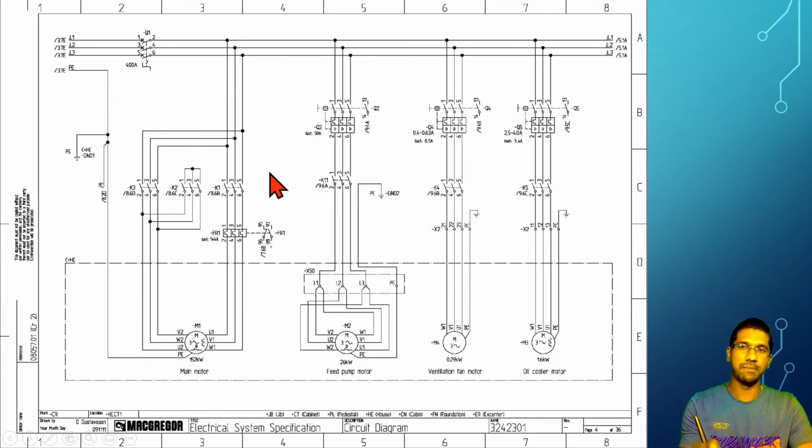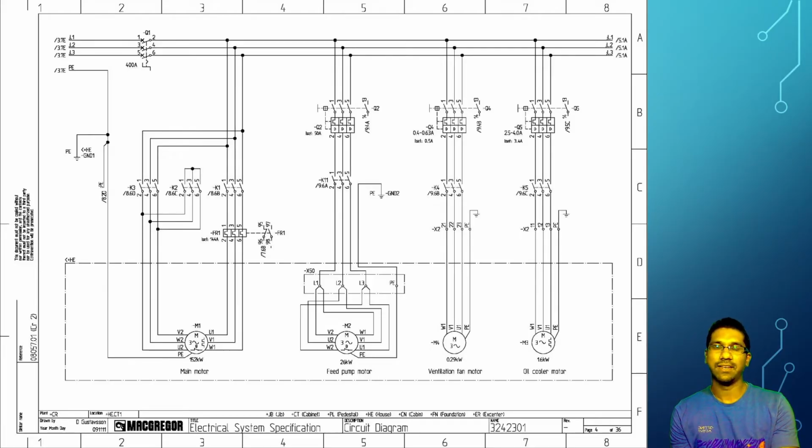If you want to find a component, there are many components in this diagram. Don't worry. Usually an electrical drawing comes in bulk, which means it has many pages, and may be combined with other pages. In a manual, these electrical drawings are given as a separate set. In the first pages, they usually give all the symbols and which symbol is related to which. You don't need to keep it all in mind, but you should have a basic idea of these symbols.